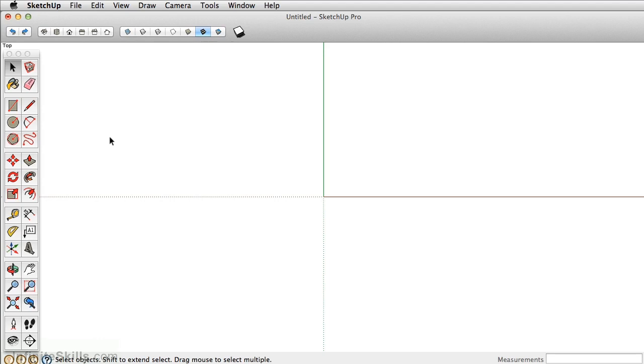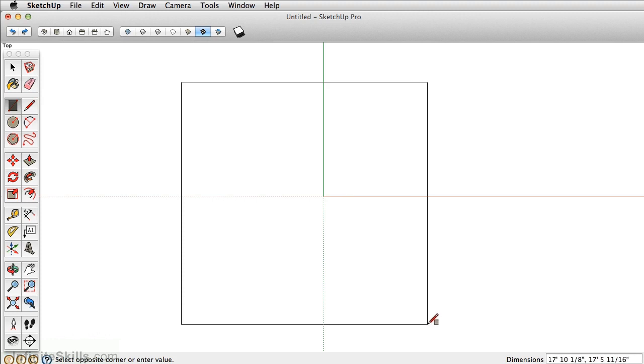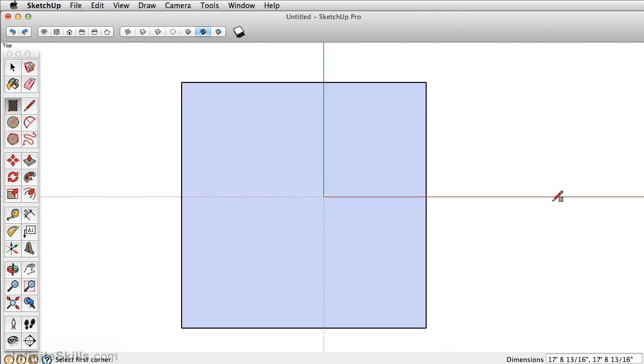Before we use the Arc tool, let's go ahead and just draw a square in our model space. It doesn't really matter the length of it. I just want it to fill up the space. Now to use the Arc tool, which is located right here, it's also A as a keyboard shortcut. It's a 3-click process. And like the Polygon and Circle tool, it has a number of sides. For me, I never really change this number of sides. If you're doing more detailed work, you may find that 12 sides is too many. Really depends on your specific workflow. But for me, 90% of the time, I don't change this.